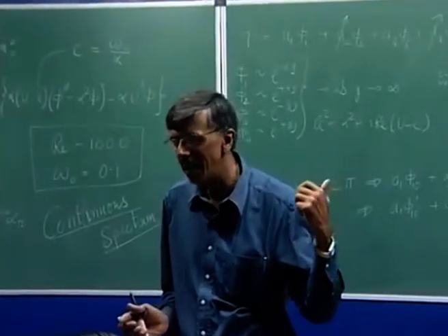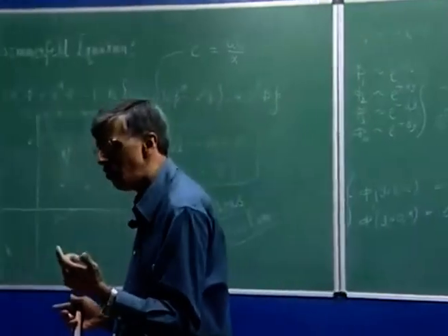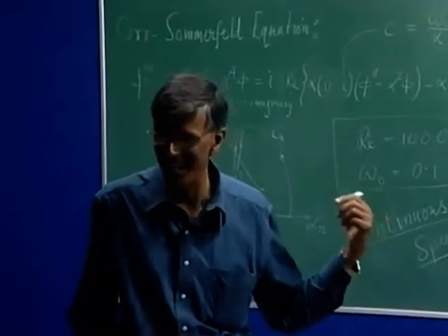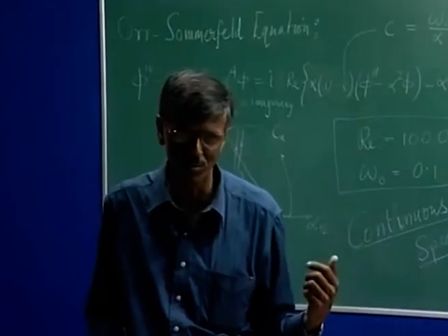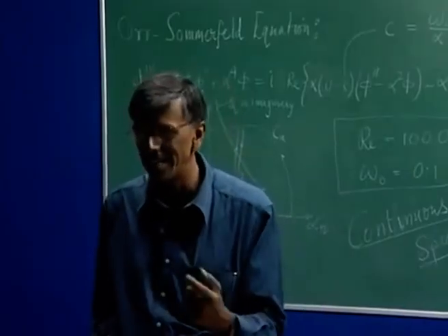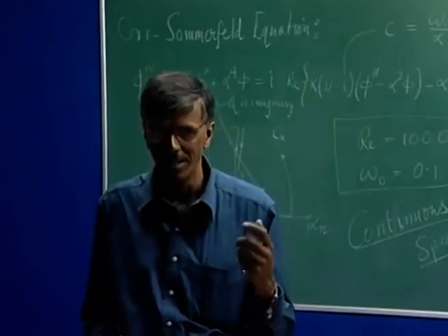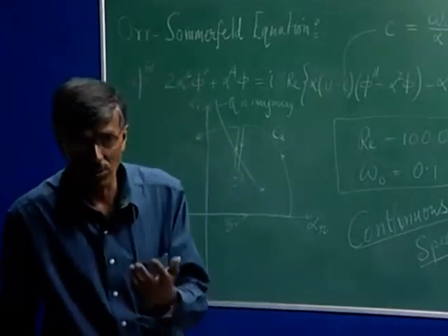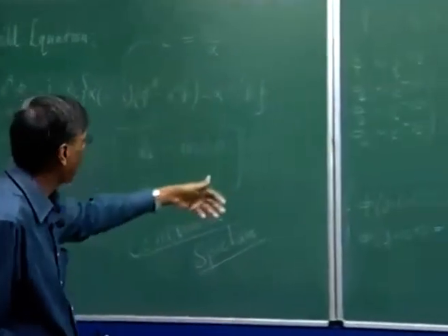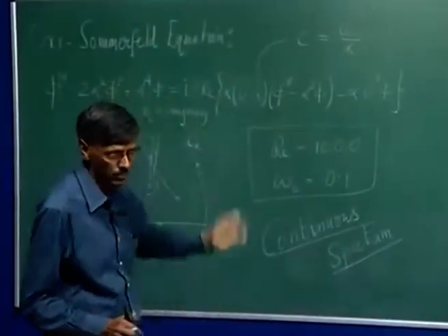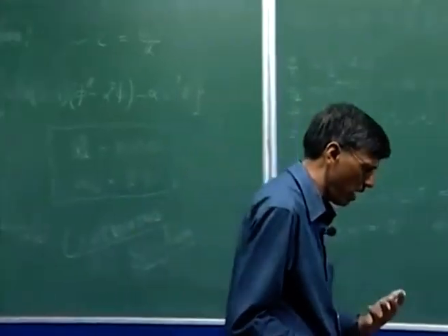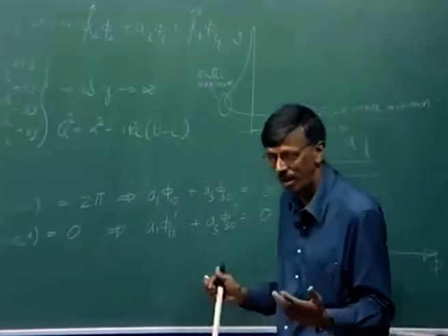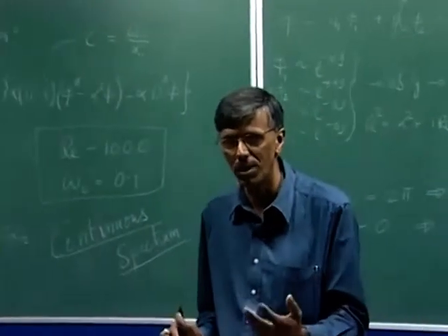But that's not a very good thing to assume a priori, right? Because A1 and A3 can become functions of y for some other reason, not for the linearized Navier-Stokes equation with parallel flow approximation. We will see that later, that when we do non-parallel theory by solving the Navier-Stokes equation, we would see that there is an additional dependence on y, but that is not apparent directly from the Orr-Sommerfeld equation. I know these are not such easy concepts, but we need to get used to the idea of analyzing and saying what is feasible and what is not.